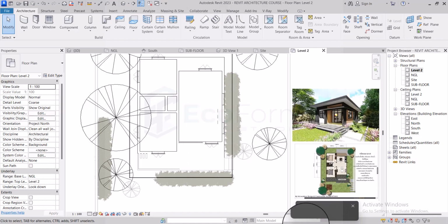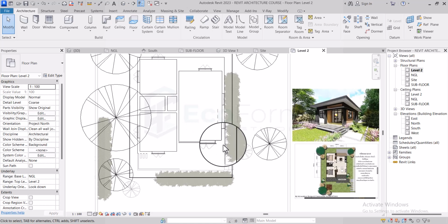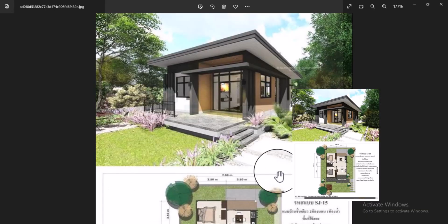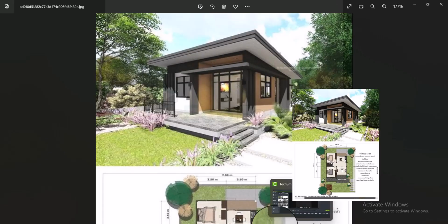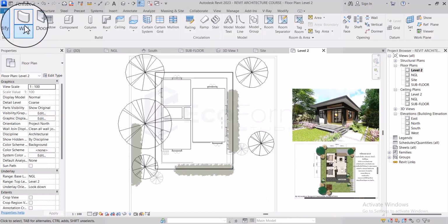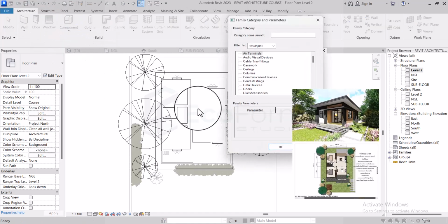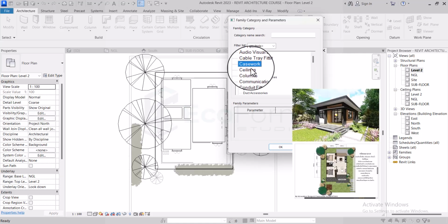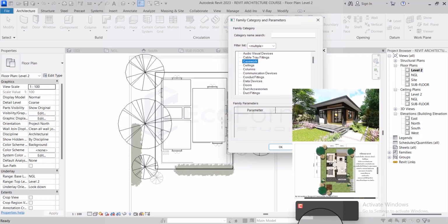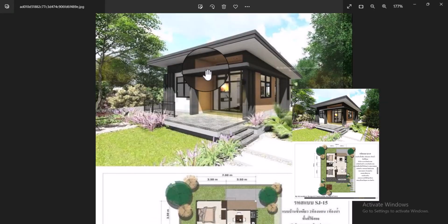So it's a wall that we are going to use to create the vertical one, but I'm going to use sweep to create the horizontal part, this one. So now come to the project, come under the Architecture tab, come to Components, Model In Place, Casework, or we can use, if we are going to be putting a bulb underneath here, you are going to have to use a ceiling component so that a bulb can be placed easily.